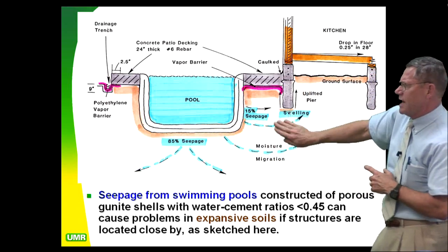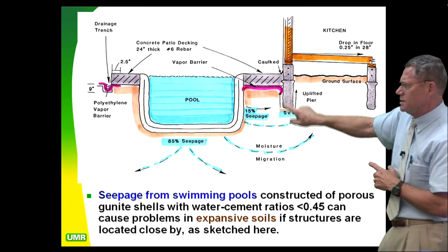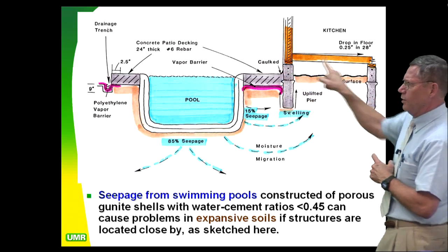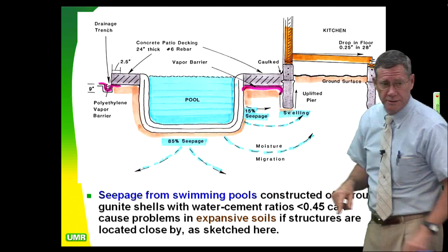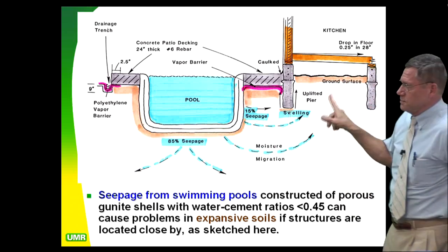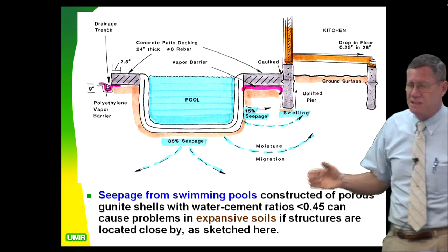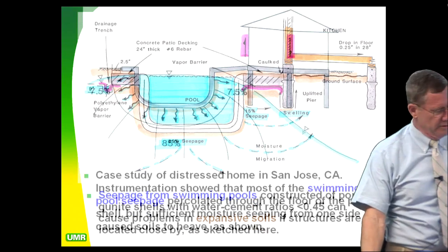And it was just this outside line of stub piers, these were only 42 inches deep, that lifted up. And that was enough to drive him nuts because his bowling ball was rolling across the kitchen. Kitchen was in the back of the house. This pier did not go deep enough to get lifted. So it's differential heave, once again, that drives you nuts.